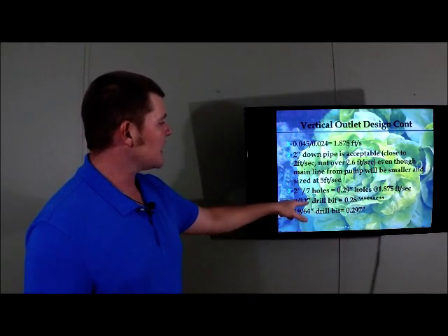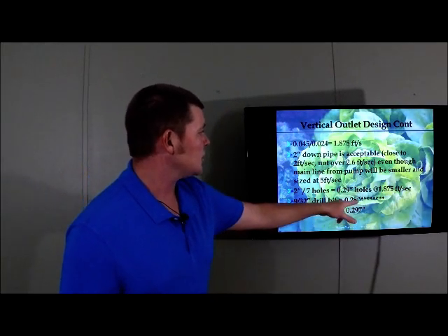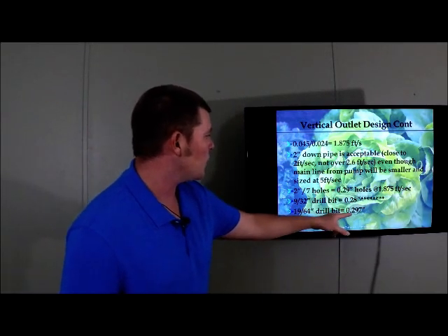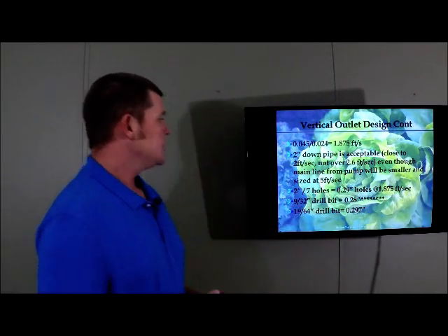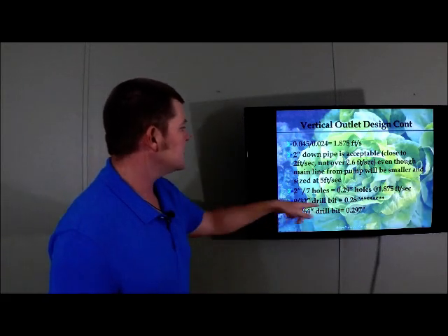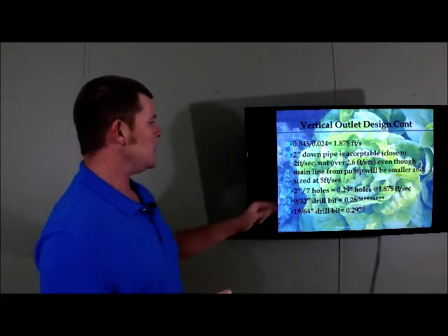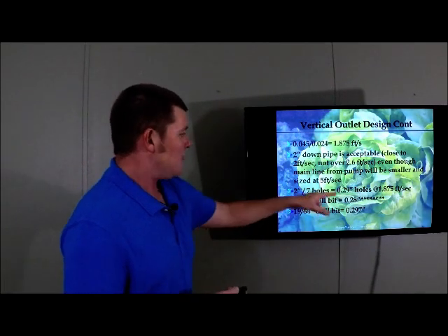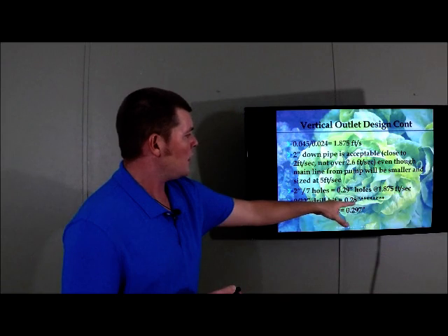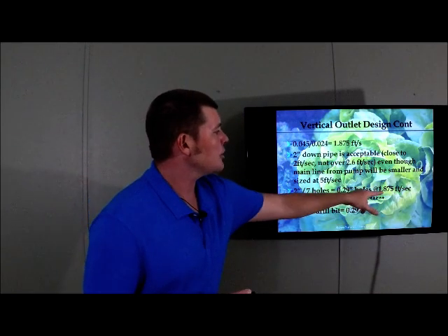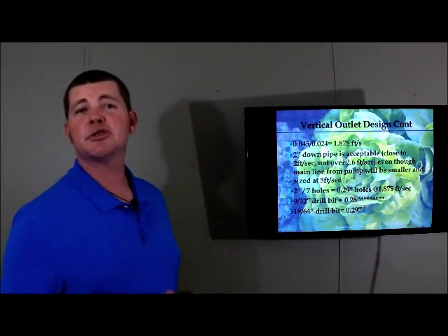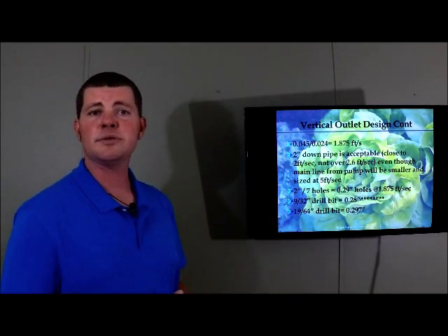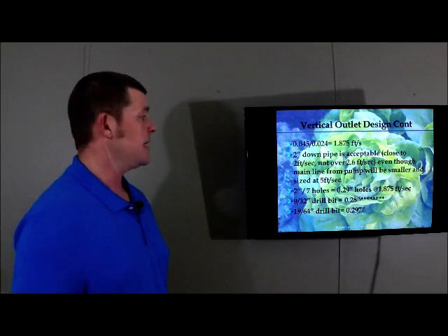So a 9/32 inch drill bit equals 0.28 inch. A 19/64 inch drill bit equals 0.297 inch. So personally, I would choose the 0.28 because if we know at 0.29 we're getting 1.875 feet per second, making that hole just 1/100th smaller is actually going to increase this just slightly, and that'll be closer to our 2 feet per second. So we would choose that drill bit, drill our 7 holes, and you have the manifold that you wanted to make.